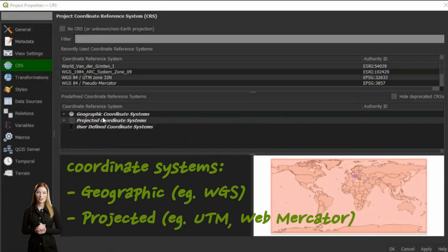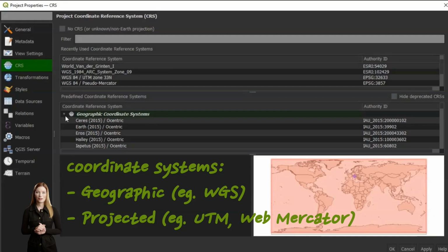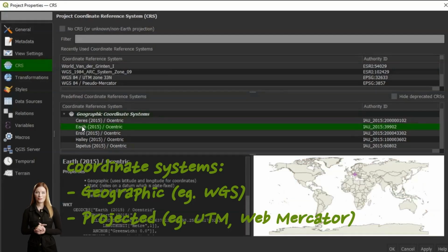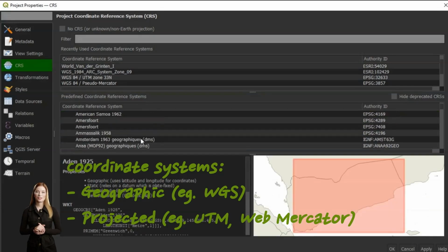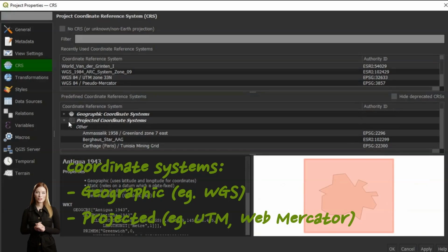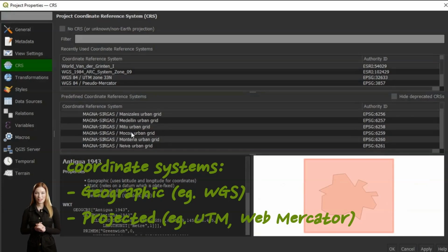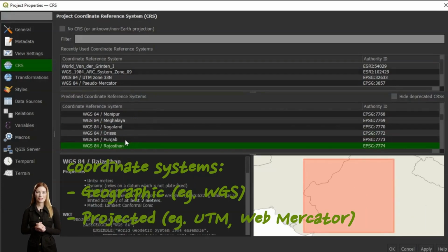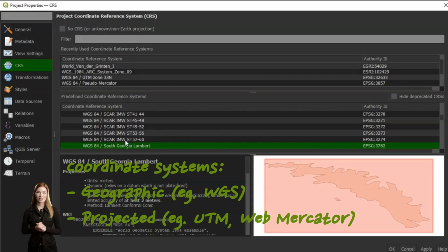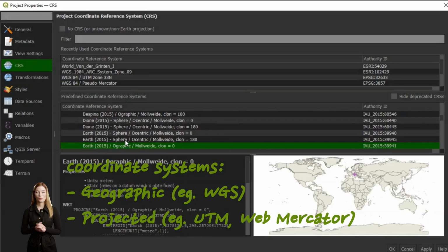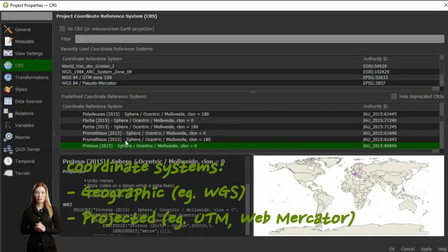We need different coordinate systems because of the curvature of the Earth. There are two primary types. Geographic coordinate systems account for the Earth's spherical shape. Projected coordinate systems transform the curved surface to a flat plane and do introduce significant distortions, although simplification is needed to approximate the Cartesian system. The distortions to distances depend on the type of projection used and are either introduced in polar regions, mid-latitude, or equatorial.